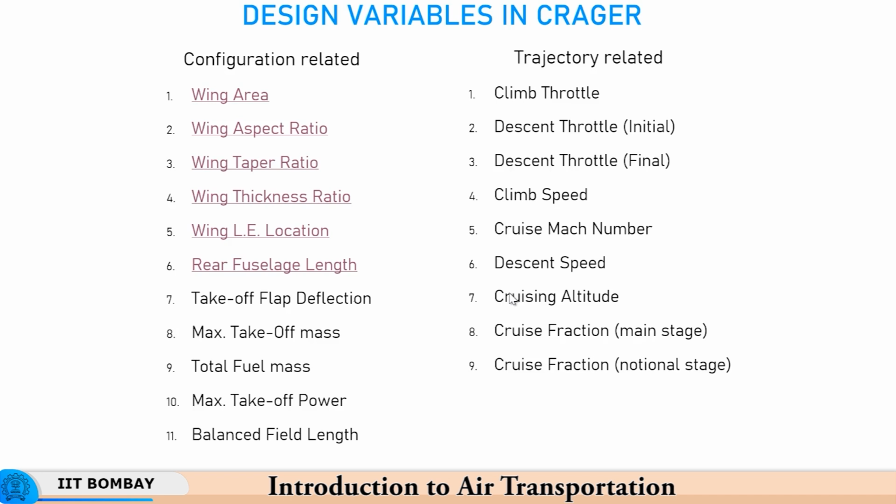Now, as the aircraft becomes lighter, even if you travel the same distance, you will consume a lesser amount of fuel because you are lighter. So, assume a case where you go from A to B, B to C, C to D, D to E, and all of these are equidistant. And if you carry the entire fuel in the first segment itself, because there is no refueling facility available, or there is no time available to refuel because you want to hop multiple times quickly, then the fuel consumed in the first segment will be much higher than that in the last segment, because the aircraft is much lighter in the last segment compared to the first segment.